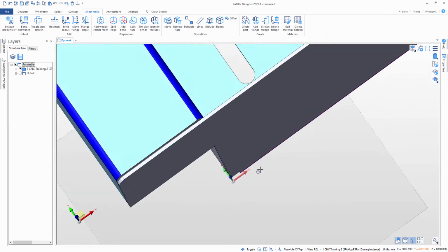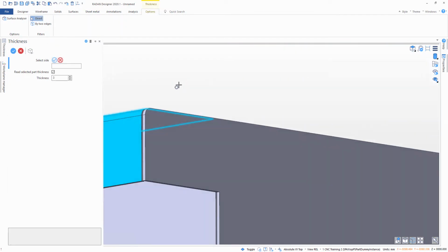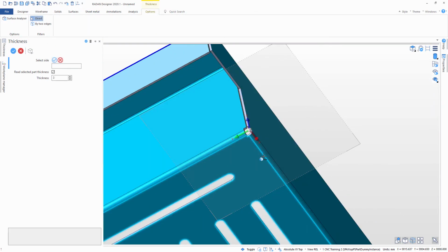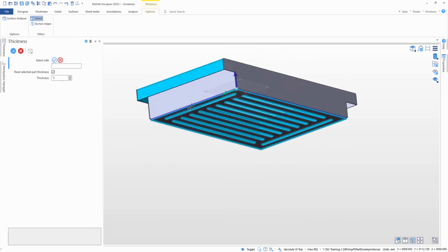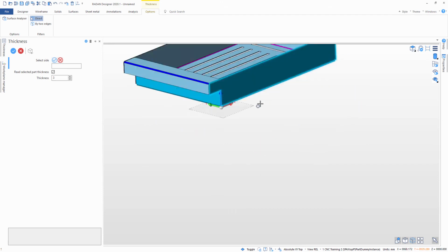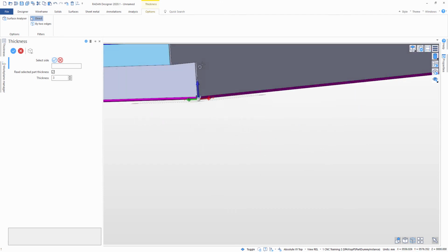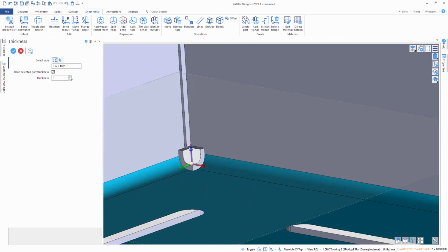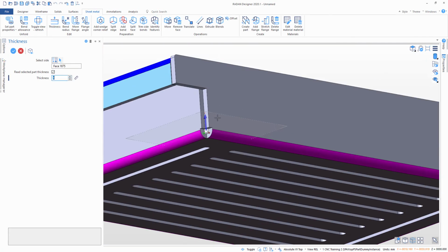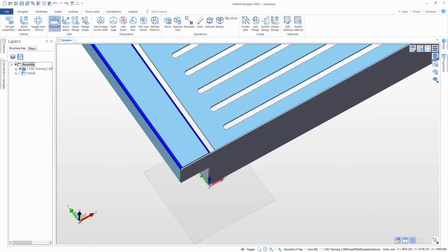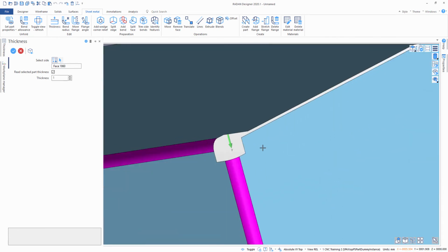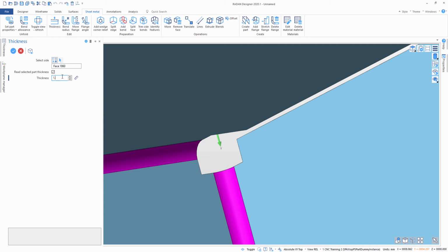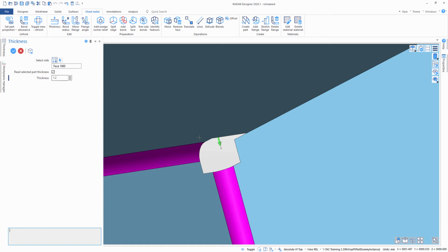The interesting bit is that it matters if you click on a model from the outside or from the inside. You can see whenever you hover on it, it just highlights blue the outside or inside side. So if I click on the outside, obviously material gets added to the outside. If I click on the inside, material will get added to the inside, but because there is not a lot of space, I will just gradually increase that thickness so you can see what's going on.